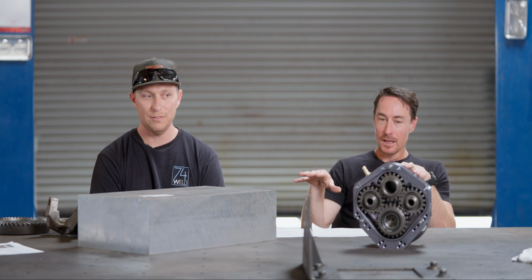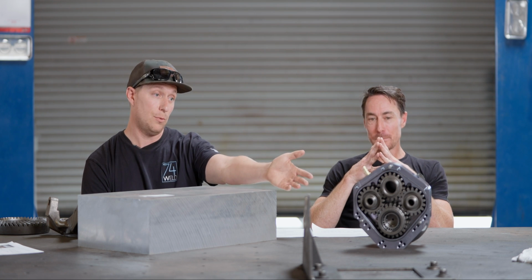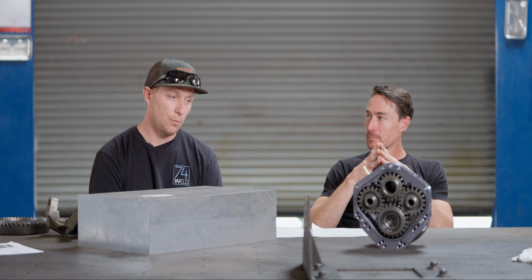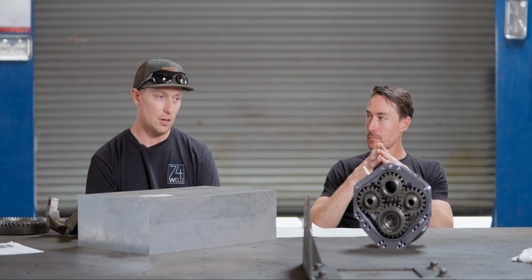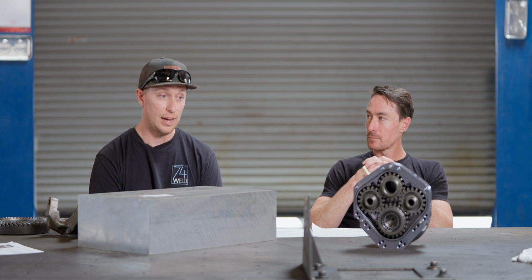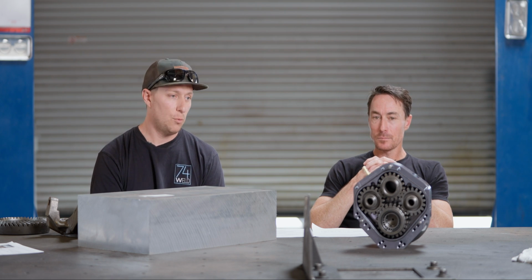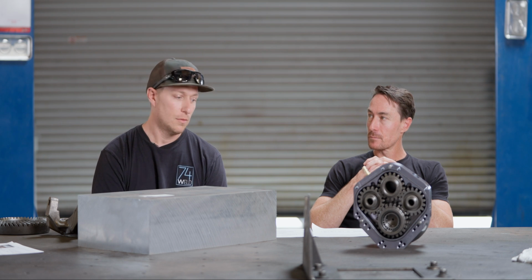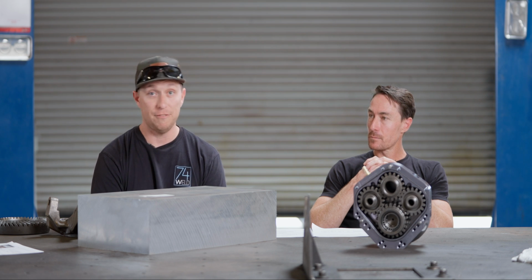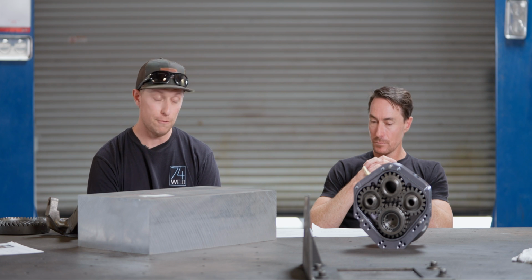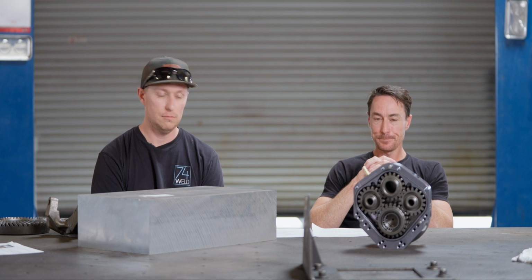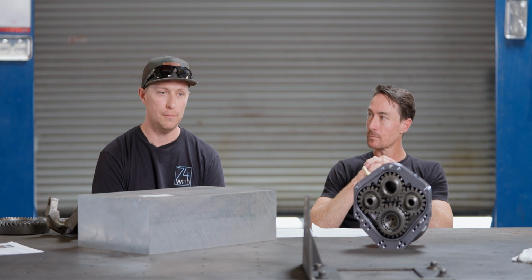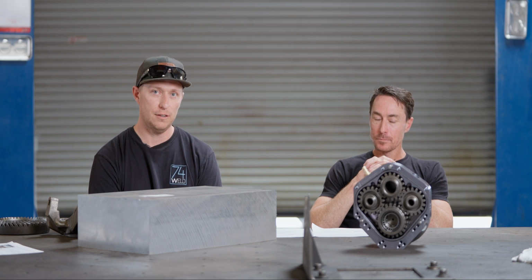Definitely. And then even just looking at, say we have this 6061 box right here. Say we want to make that out of ductile iron, on top of the manufacturing side of it. Let's say we just changed material on this. Well, your strength is going to go up by 5 KSI, from 40 to 45 yield. And to be clear, we use yield for the most part because you're not plastically or permanently deforming the material.